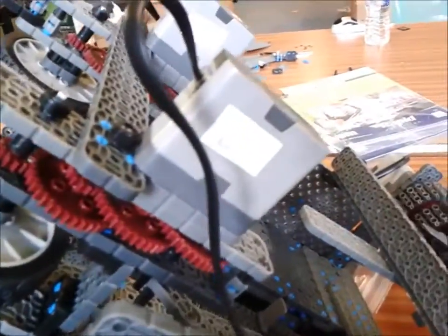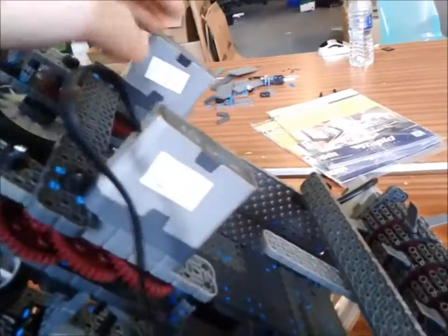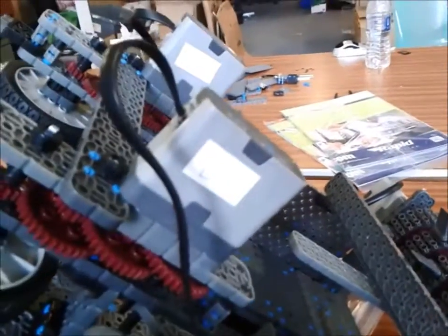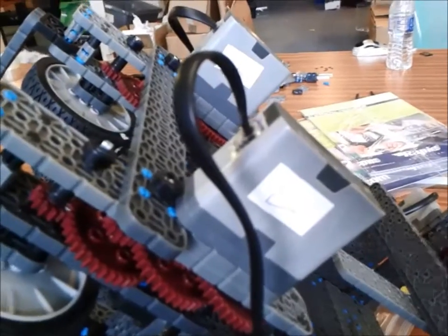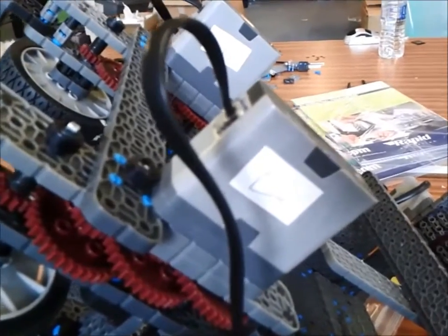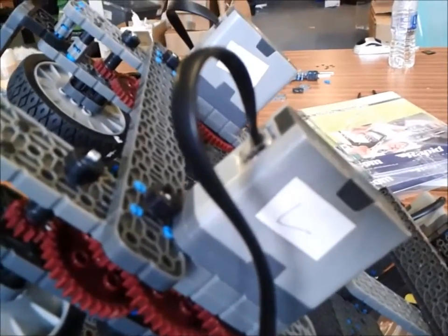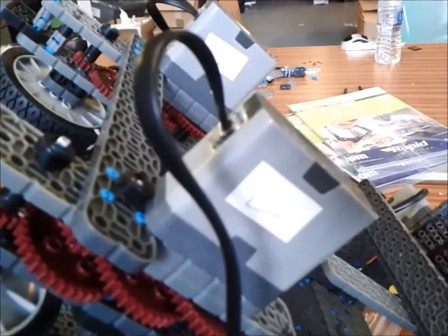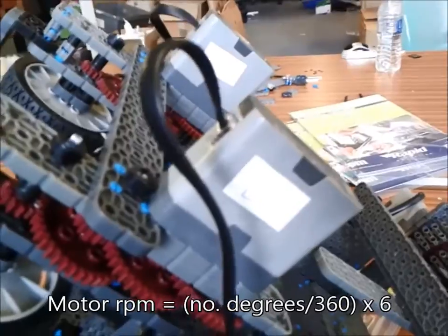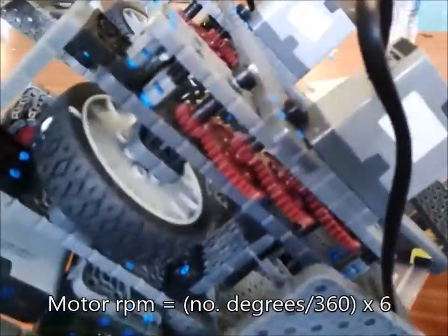The program winds the flywheels up to speed. Once they hit full speed, it resets the motor encoder count for each motor to 0 and starts a 10-second count. At the end of the 10-second count, it stores the motor encoder value, which is the number of degrees that the motor has turned in that period. We divide that by 360 to give us the number of complete rotations in 10 seconds. Then we multiply that by 6, because we want 6 lots of 10 seconds to give us a full minute. That's how many rotations we've done in a minute, which is our RPM, revolutions per minute value. That's what the program does.